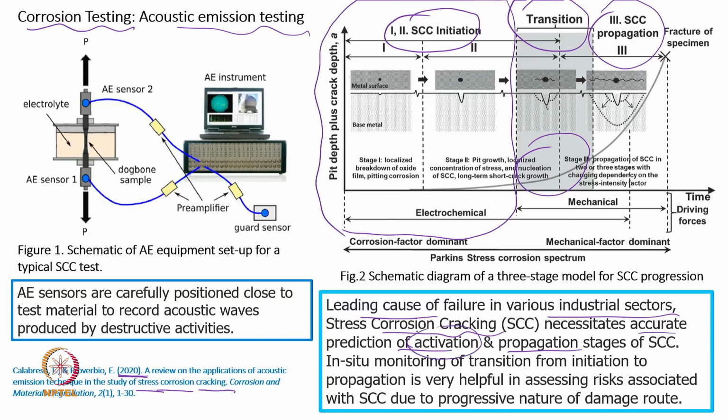Even if there is an activation or a start of a crack, or, as I mentioned, cracks and irregularities on a surface, the question is: are they noticeable, and are they sufficient to increase in size? If they are not sufficient to increase in size, and some additional energy or corrosion mechanism is needed, then we do not have to worry.